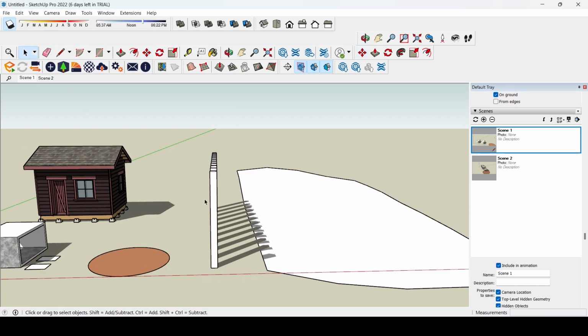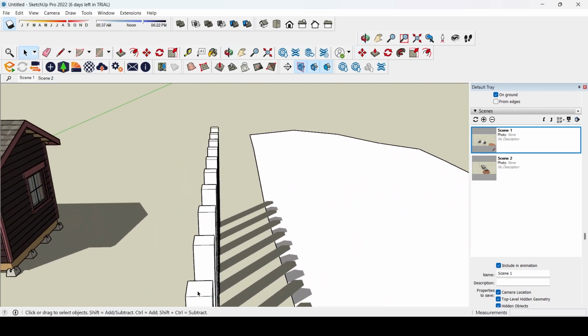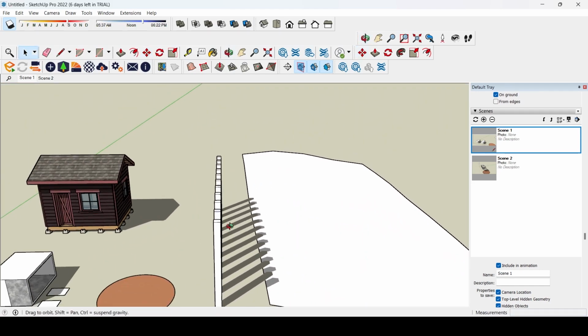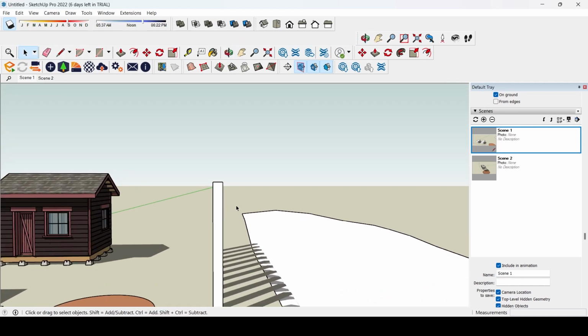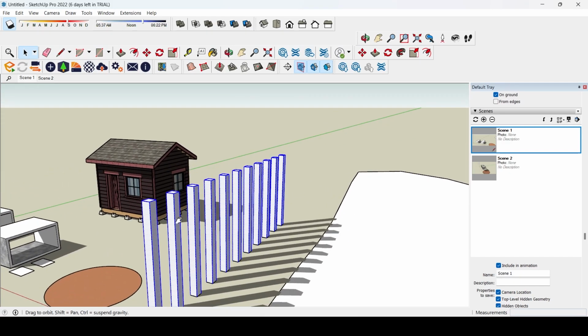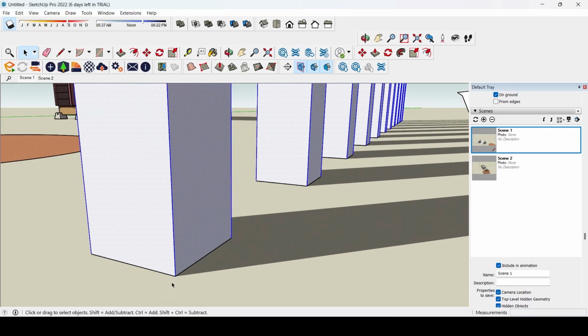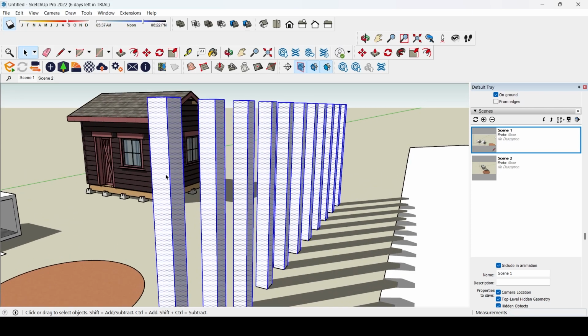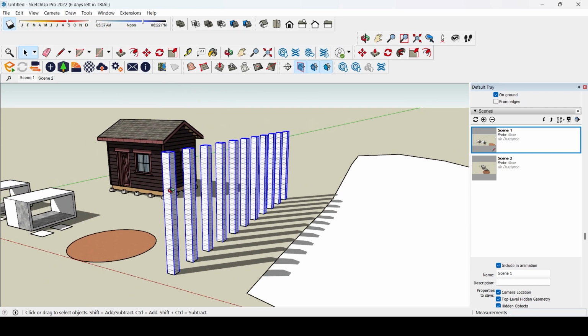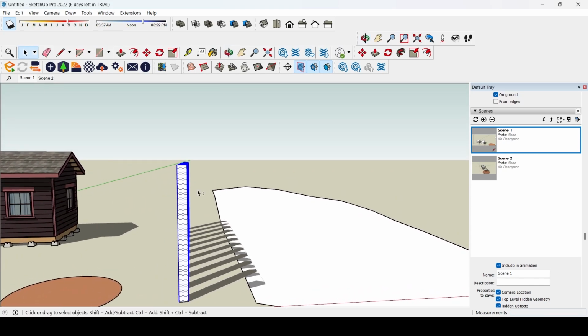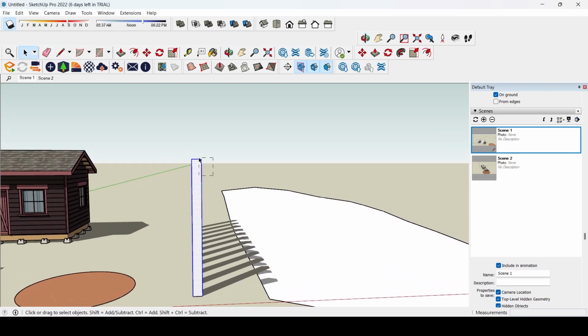Let's say I wanna mark only the top face on each of these, right? So if I go to this view, if I were to mark it from here and upwards, you see I get almost all of the geometry except for the bottom here. And that's because all of these faces and all of these lines here, this square touches them.